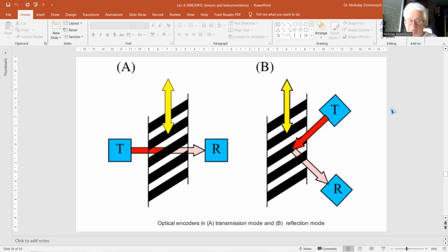The acquisition of absolute position with a resolution of n bits requires at least n optical tracks on the encoder and the same quantity of separate sensors. Obviously, the maximum resolution of an absolute encoder is set by that of the least significant bit, LSB, track, and evidently it is the outer track of the angular encoder. The practical resolution is limited by the dimension of the detector.